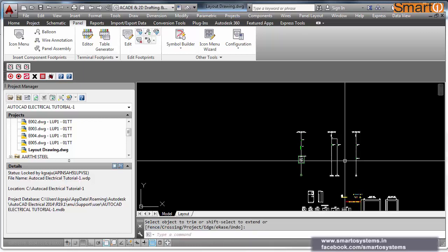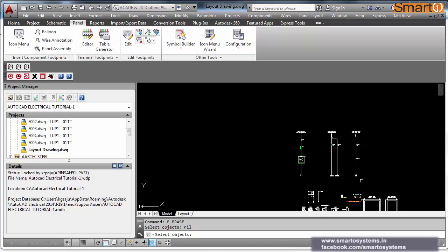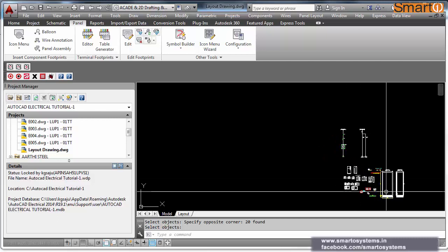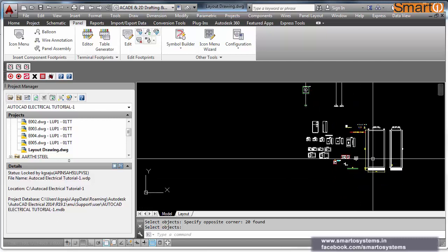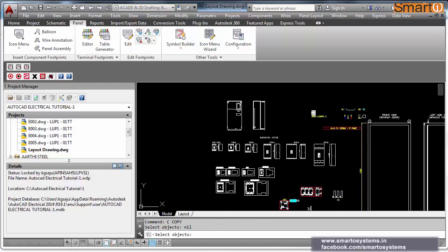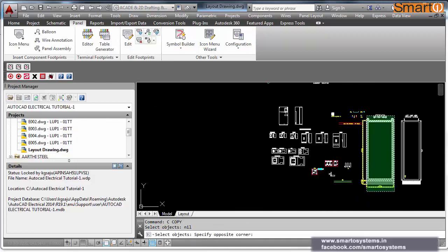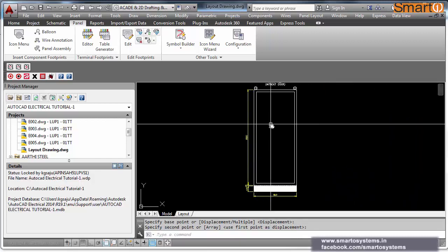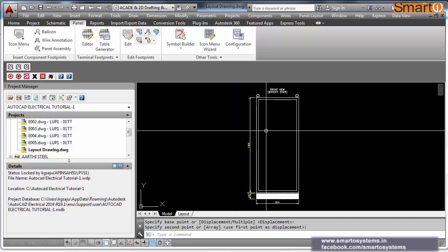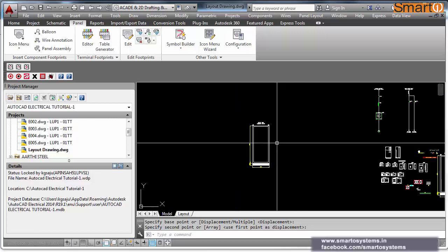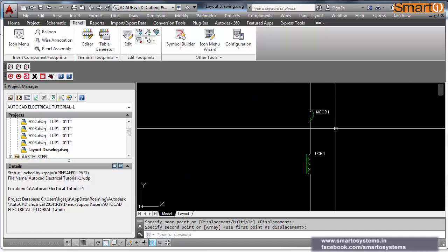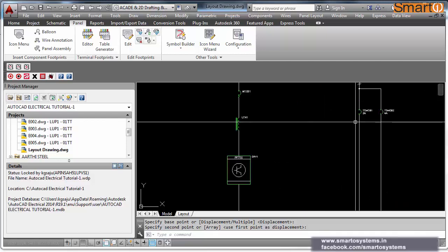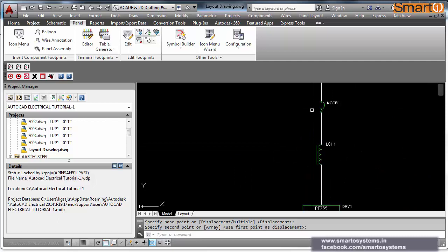So from my library, I have copied all the blocks into a single sheet which is necessary for me, including the panel. Now what I will do is create a drawing in this sheet, keeping all the blocks aside. This is my panel, front view of my panel without a door. Now I have to place an MCCB, line choke, drive and 2 MCBs. That's all.